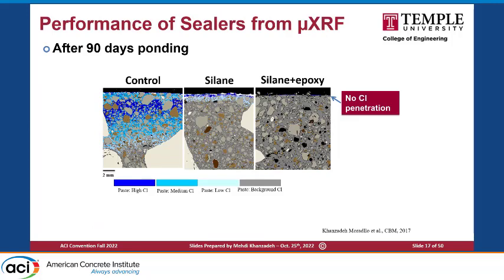This is one very quick application of the micro XRF. We had different samples. On some samples, we applied silane sealers, on another silane plus epoxy, and we had a control sample. We exposed them to the chloride solution, and you see the difference in penetration after 90 days. So you can see, with a high spatial resolution, the impact of these different types of sealers on your penetration depth.